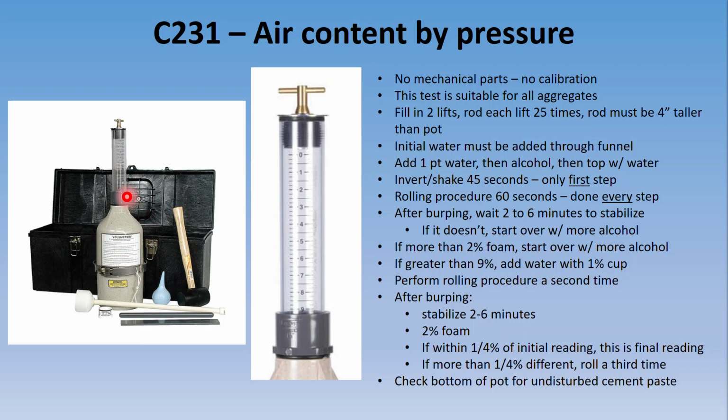And then when you've got that sealed, before you start adding in your initial liquids, your water, you want to put that funnel in. And that funnel's purpose is to disperse the water so that it doesn't splash and create any kind of entrapped air pockets in your concrete sample that you took time to prepare. So I see that a lot. People will forget to put that funnel down in the neck before they start adding their water. So make sure you remember to do that. So that's this step right here.